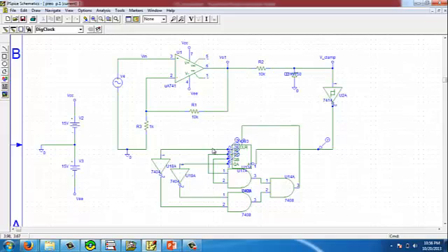What I have used today is to create a decade counter using this simple ripple counter module. A decade counter is one that counts in decimal digits rather than binary. Counts from 0 to 9 and resets to 0. The counter increments on each clock pulse until it reaches 1001. When it increments to 1010, the input goes high, which will clear the counter to 0.